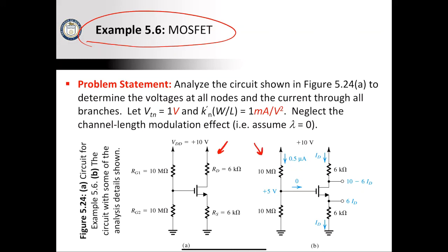You can see there's some stuff that we can really pick off very easily off the bat. We always know that the current flowing here is going to be 0 for a DC system at least. Therefore, these two together are going to work like a voltage divider, and so the voltage here will be equal to 1/2 of 10 volts, so that's 5 volts.